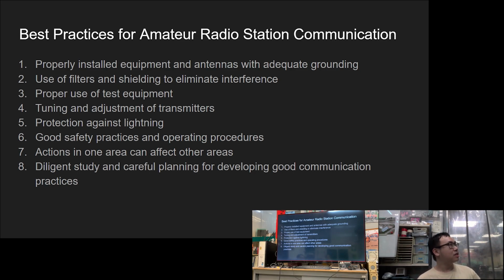Test your equipment so that you make sure you are calling the radio on a correct frequency. Adjust the transmitter tuning. You don't want to damage your radio station. If you have poor tuning, we will mention the standing wave ratio (SWR) in later lessons: if you cannot emit your signal properly, some power will return back to your station.